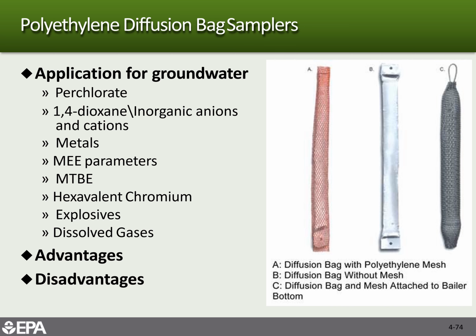It's fairly simple. You just drop it in the well to a certain depth, and it relies upon maybe a 4-week time period for the water that you put in the bag to come into equilibrium with the water that's moving through the well. So it doesn't generate any investigative derived waste, which is one of its big advantages. And it's a fairly labor simple kind of a process.